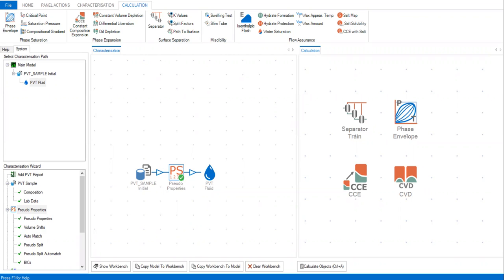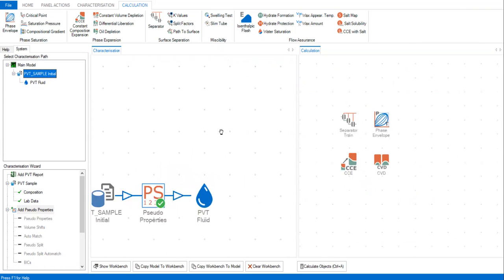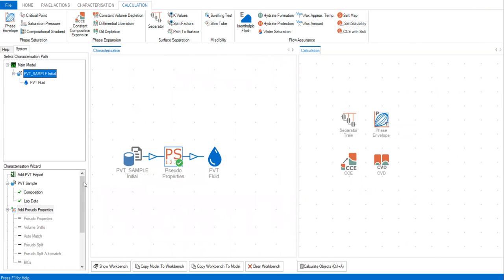All right, now we reach a point where we will perform primary regression. We will perform the initial regression on the liquid density, saturation pressure, and separator density, as well as the GOR, which will act as the anchor point using critical temperature, critical pressure, binary interaction coefficient, and also the volume shift of the pseudo component.